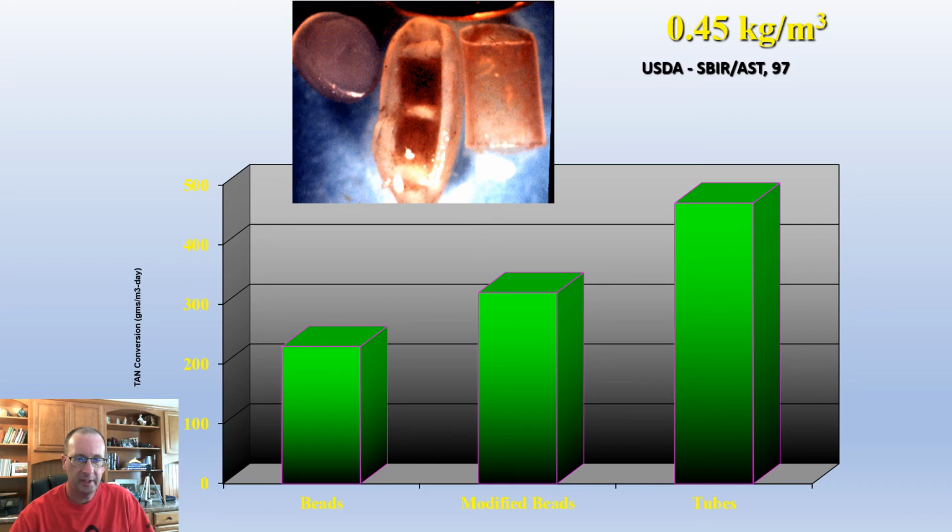And as you can see here on the right, the best design, ironically enough, is really a coffee straw that's been cut into really small pieces. The problem is that it clogs up almost immediately, and so even a backwash cycle wouldn't clear it out. The one in the middle, that little bean looking thing, that's what's in the middle of our polygeyser, and that has enough channels and surface area in it that it can bring you a fairly high level of nitrification per cubic meter of media, but also that it can actually be cleaned by a good backwash cycle.